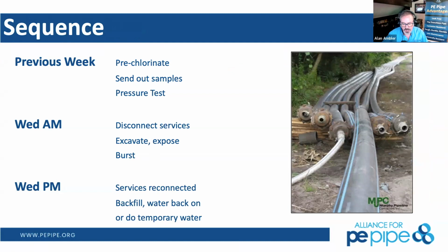We really don't want a grouted pipe connection like you would in CIPP. And pipe bursting for gravity sewers, as Ruth had mentioned earlier, on a high slope condition, that grout was a weak point and pulled out. If we know that we have a sensitive joint with a manhole, we either go with a high-density polyethylene manhole, which is cool, or you can make sure that you further restrain that pipe through mechanical restraint or thrust block right at that specific high-slope scenario.